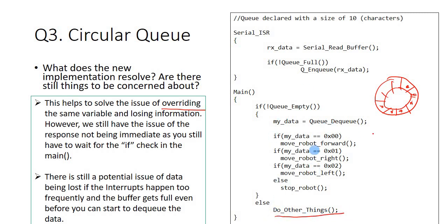If you look back at the same timeline, if after the if check I go and do the else, and during this period of time I can have multiple interrupts, it doesn't matter. Each time the interrupt comes in, I will still be able to update the buffer and keep the data.